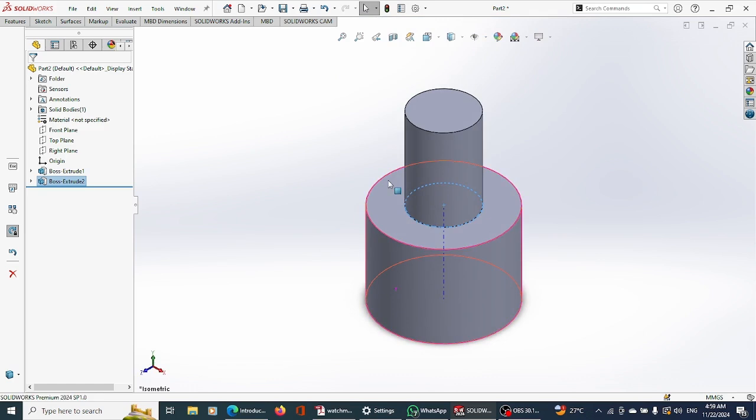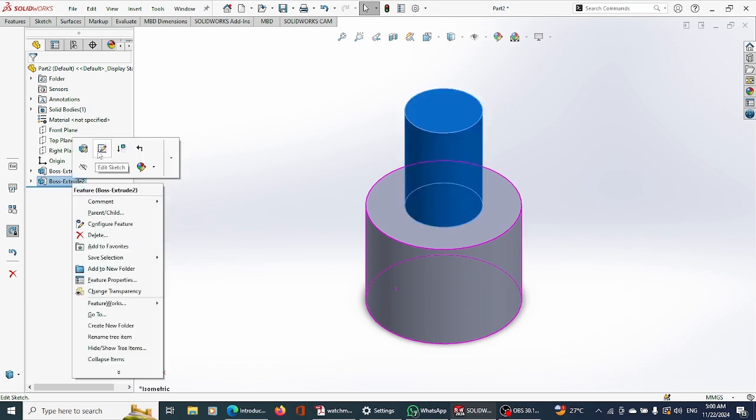If you model like this for me, I'll still mark it for you. You modeled it, whether it's lying down or it's facing. It's why, at least for now, this still works. If you don't want it to look like this, you want this top one to be under. Come here, you can edit this feature we just did. Right click on here, go to this guy, edit feature.